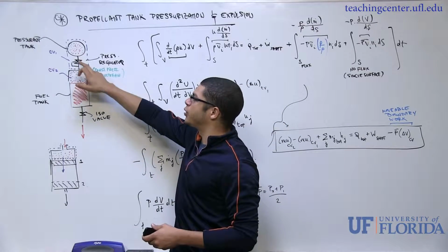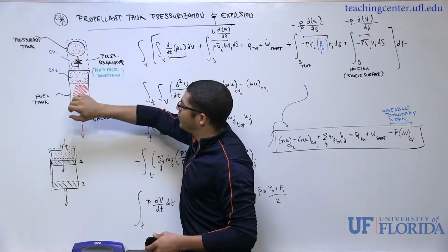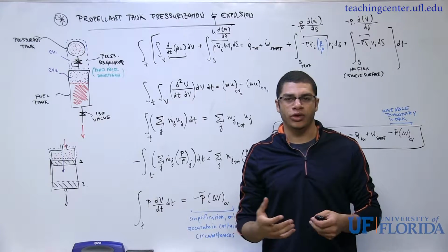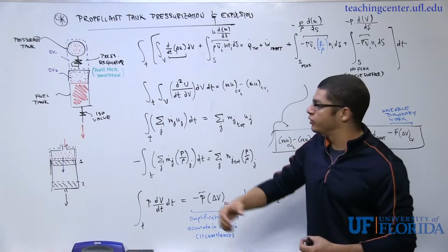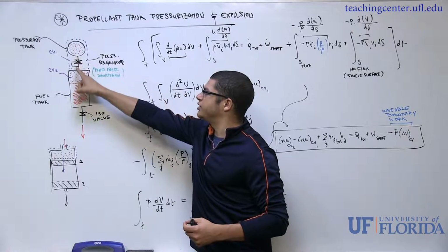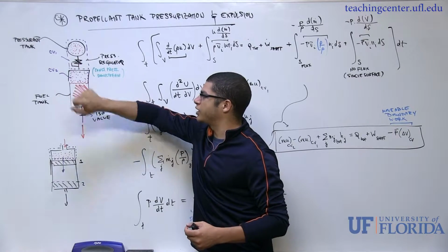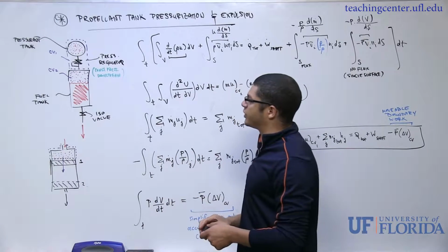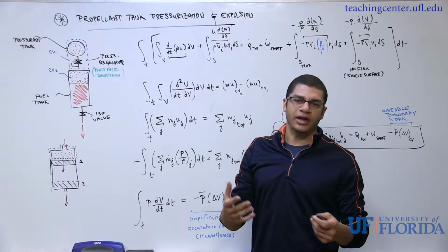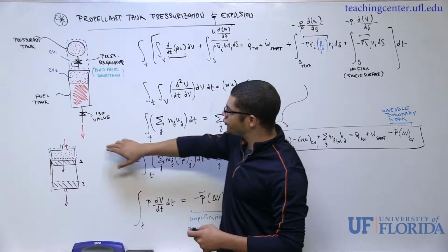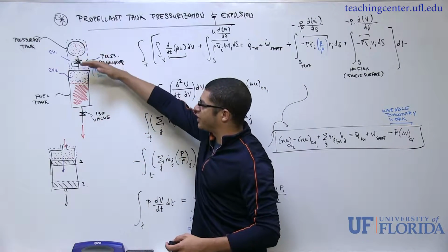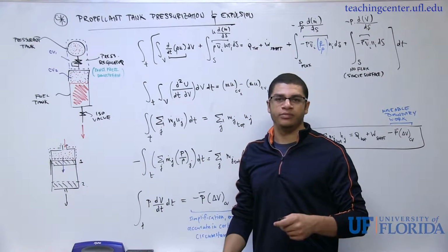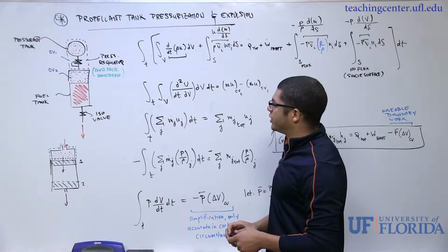And then also we've got a component between this high pressure gas tank and our fuel tank called a pressure regulator that's going to do nothing more than maintain the pressure downstream of this tank and downstream of this piping at some constant pressure that we're going to set. You could do this in real life with different types of regulator valves. Initially we'd open this valve, there would begin to be some kind of flow, and then everything downstream of this regulator is going to be at constant pressure. And we'll see in a moment why that makes life easy for us.